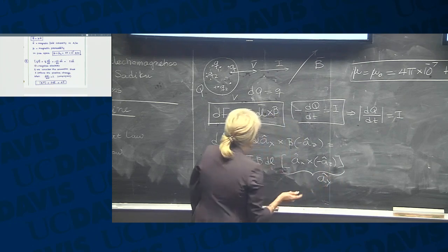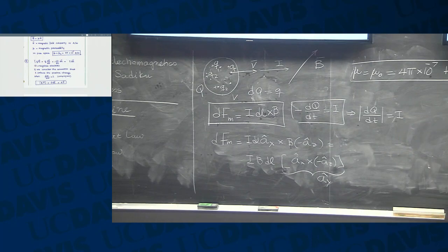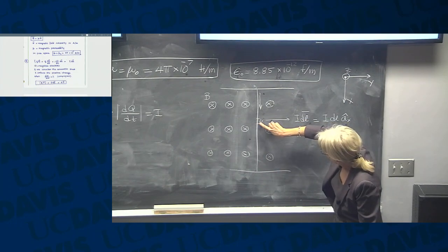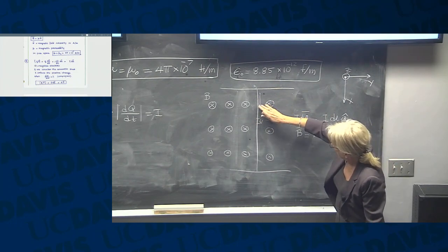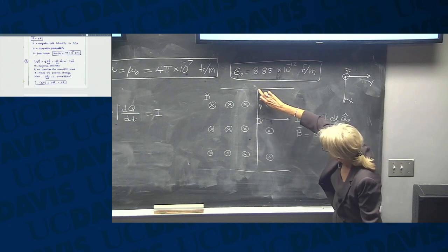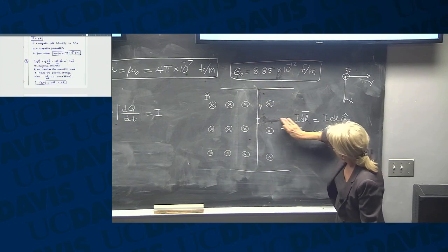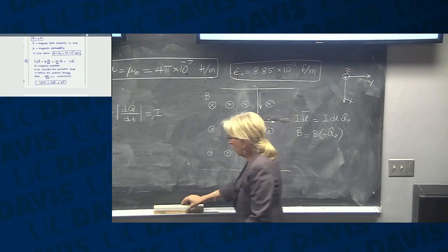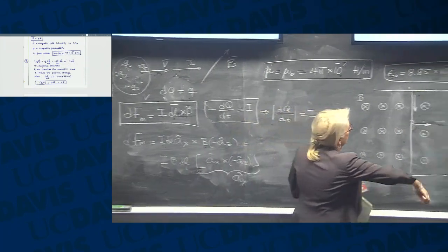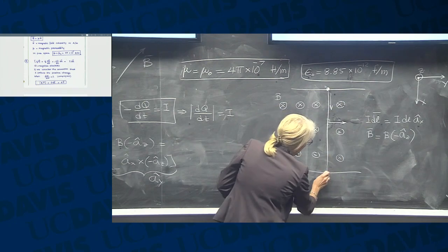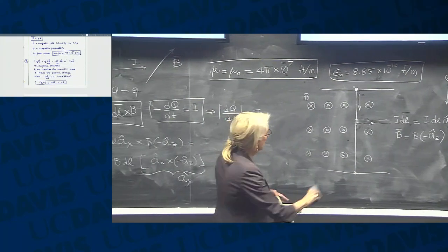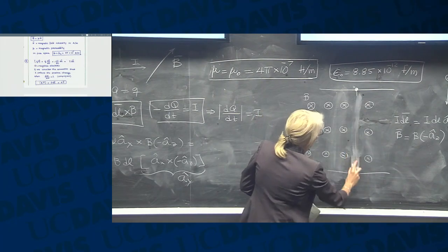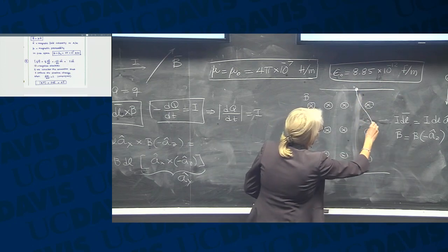AY. So I found something very interesting: if the current flows like that, there is going to be a force only on this one that goes like this. Since there is not just this small current here, but the current extends from here to here, there is going to be a force that is going to move it like this. And if it's a force that moves it like that, and these are two points that are anchored and cannot move, how is this going to flex? We are going to see a deflection of this wire like this.